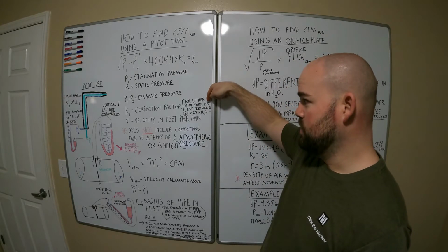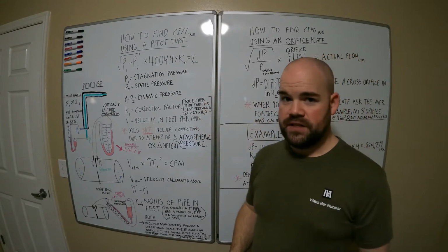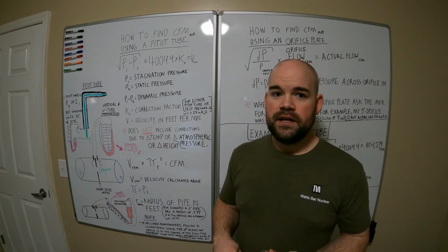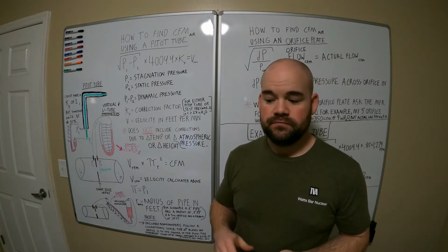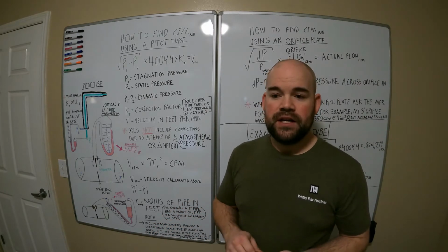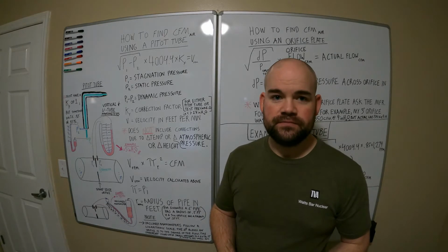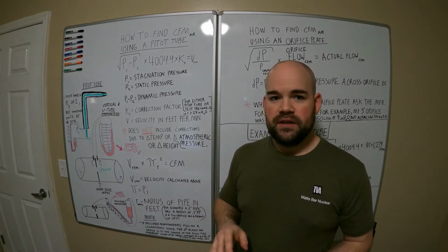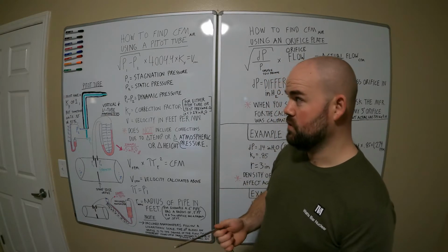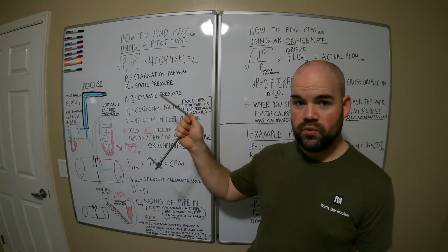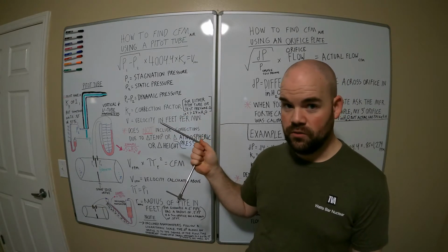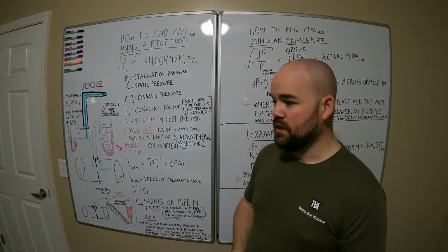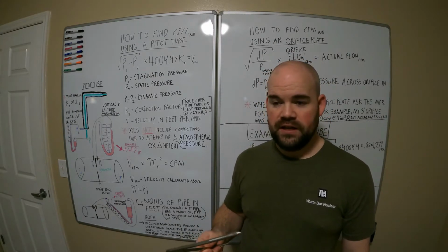What I put here for either a pitot tube or the test pressure, okay? So for example, if I am measuring my flow at 28 inches of water column, which is how I do all of my tests, if I don't have a good enough bleed valve, like I have some of those issues that I got to work through, and when I test a valve, it's at 26 inches of water. If I turn another vacuum pump on, my bleed valve doesn't get it far enough down to 28. The closer you can get, the better, because this is not a perfect science. However, if you take the square root of the pressure you're wanting to test at by the pressure that you are testing at, you can get a K factor, or a correction factor, to get that flow at 28 inches of water. And I can explain that if somebody's got a comment on that or a question on that.